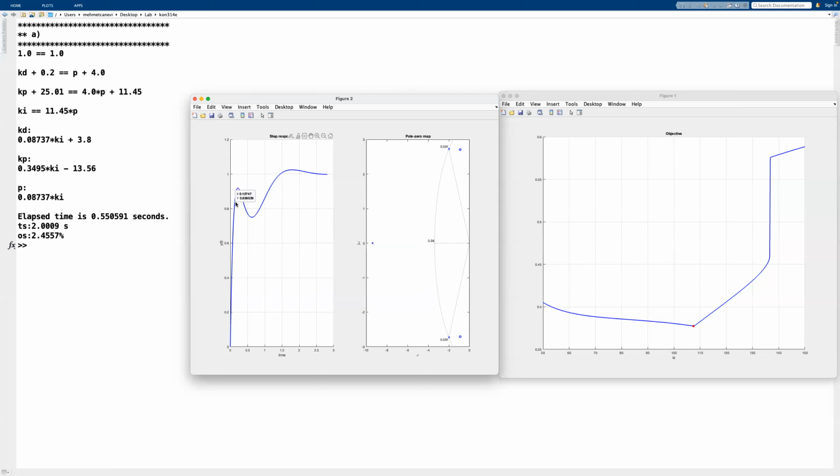Most of the time in real world applications, we want to get first order or second order degree responses. We want to see that shape most of the time, because it's more optimal that way. Boiling water would just be a first order system that, for example, takes 1 minute to rise to, I don't know, 86 degrees, and then in the second minute it would be 90 something. In 4 minutes it would be ready, and it would be boiling. So that makes more sense in terms of economy, control effort, and the shape of the response and everything.